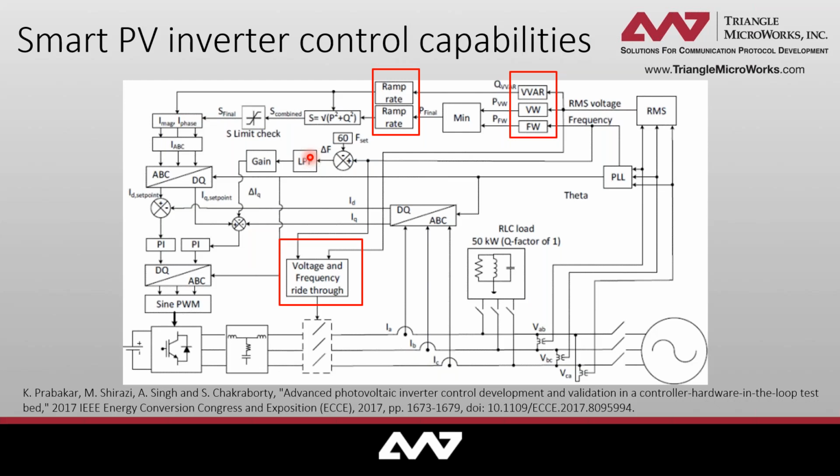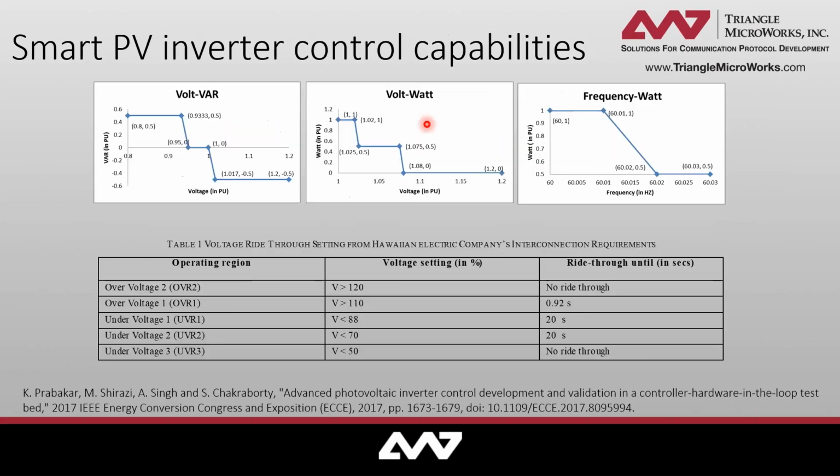So we took the smart inverter capabilities that we built for this inverter, specifically volt-var, volt-watt, frequency-watt, and then other controllable things like ramp rate and voltage and frequency ride-through, and tried to enable interoperability, allowing clients like a microgrid controller or ADMS to talk to the inverter and change these settings in real time.